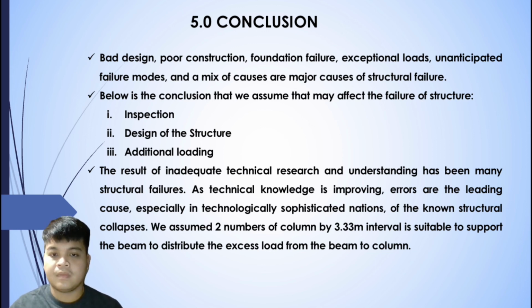First, inspection. For inspection, a regular inspection of buildings by an expert engineer for structural degradation or fault should be made mandatory every 5 years, and buildings that are subjected to such mandated inspection should be inspected more frequently. For design of structure, the design of the structure is the root and primary cause of the structure failure. The dead weight of numerous structure elements was underestimated, and a substantial number of individual structure members were grossly underdesigned according to structure analysis.